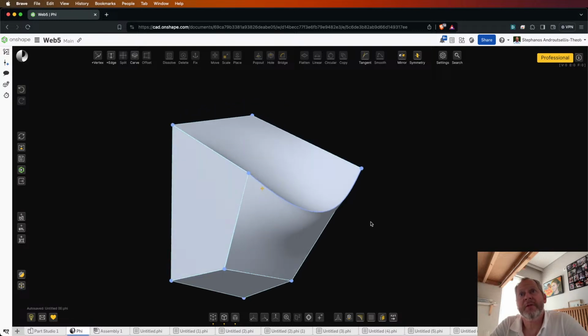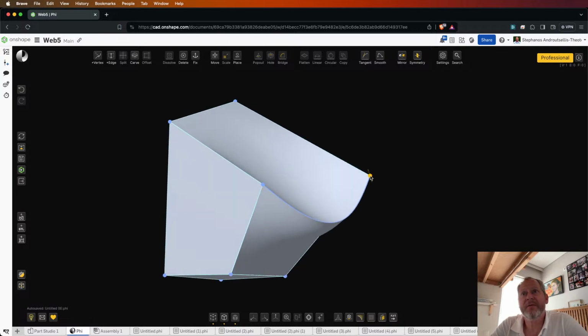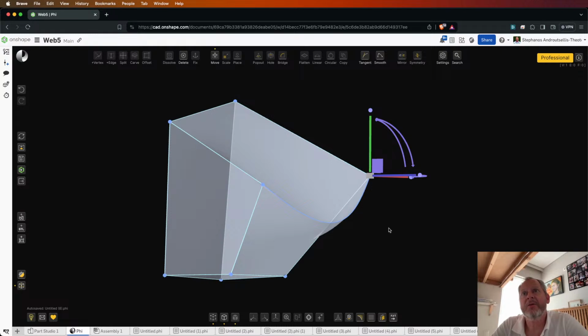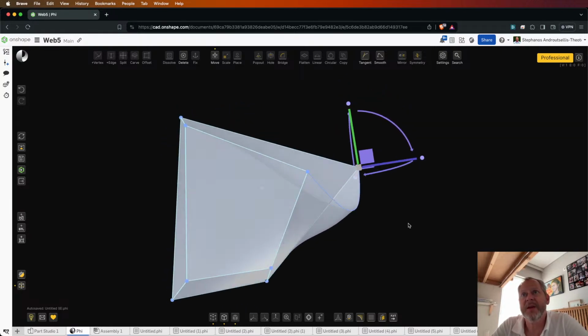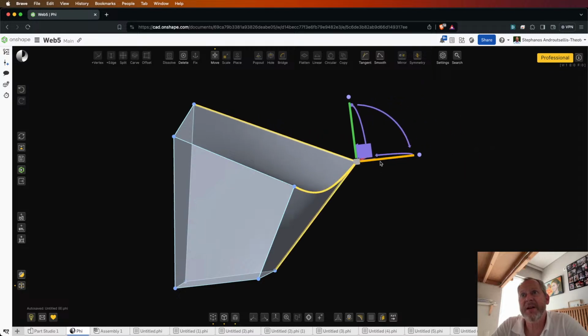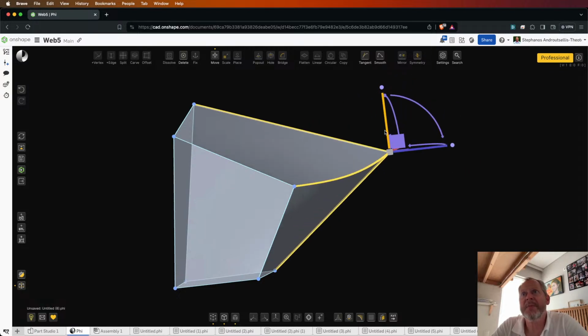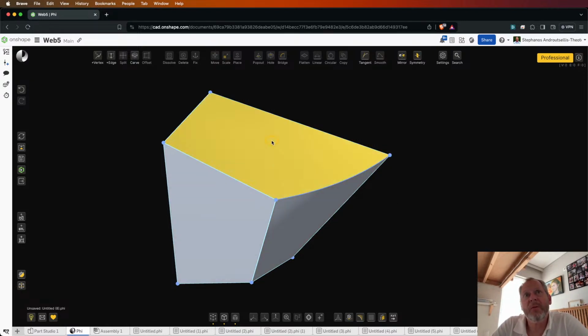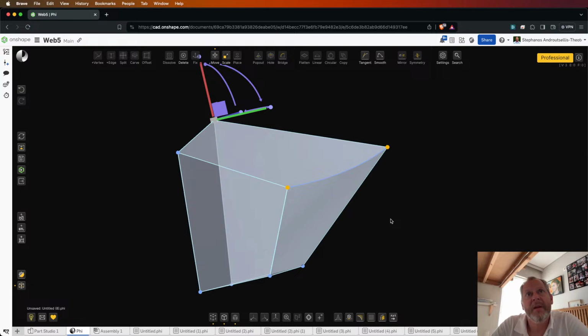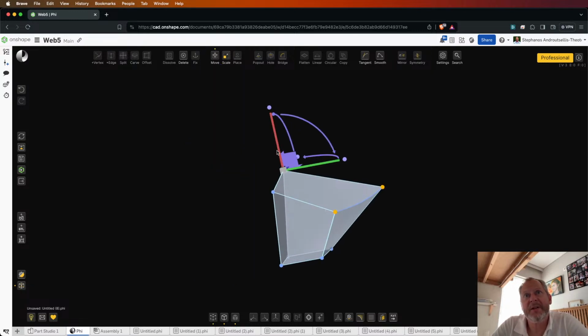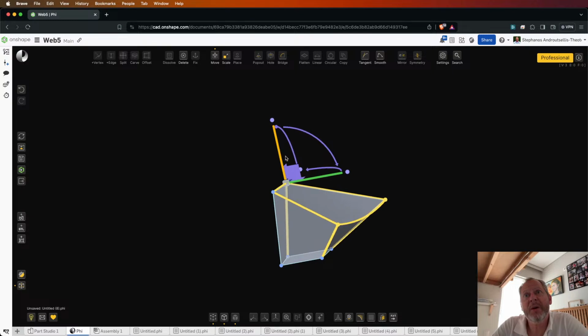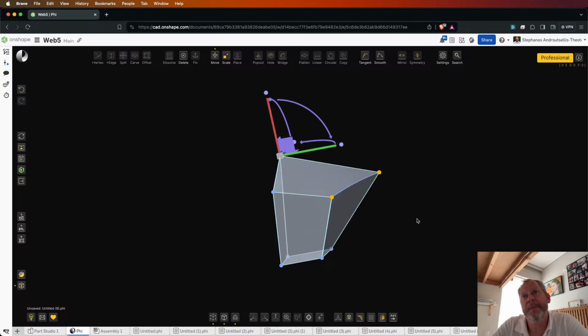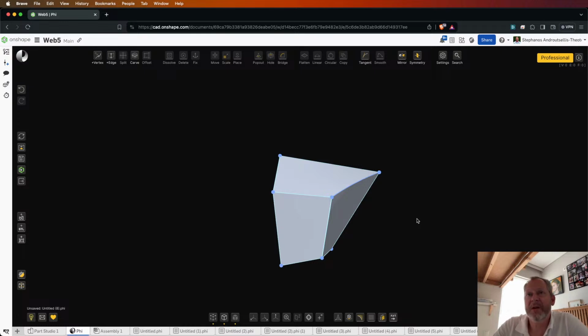Alright, now one more thing you can do is select just one vertex and hit M, and you still get the manipulator on this vertex. So this allows you to move it precisely along a certain direction, as I'm doing now, instead of only freeform moving the vertex. But one thing I wanted to point out, if I select, for example, 3 vertices and hit M, the manipulator will be placed on the first vertex I selected, but the movement will be applied to all of the selected vertices. So this is a convenience for moving many things together.